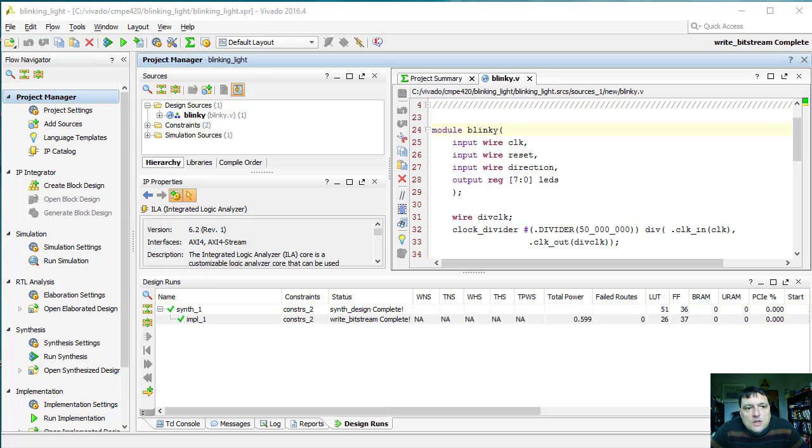So for example, maybe there's a dead short on a line and I'm actually risking damage to the part. Or there's a break in the line and I'm just not going to get the signal. So there's a number of things that we can do, but knowing where to start looking to resolve those is more than half of the battle in many cases.